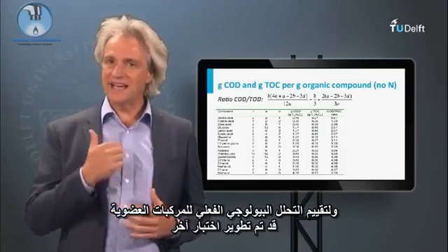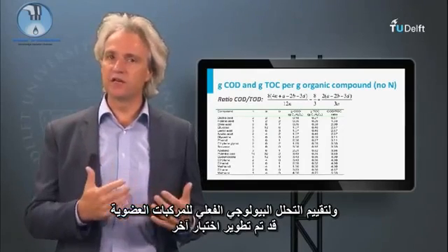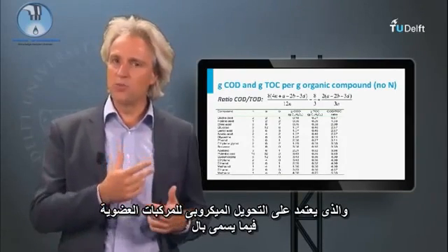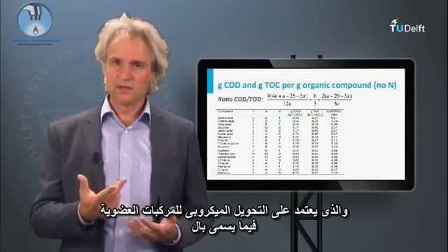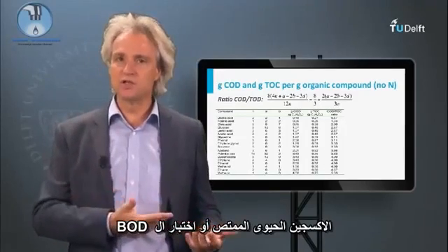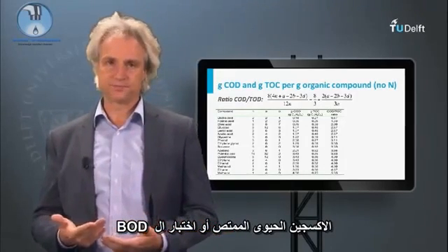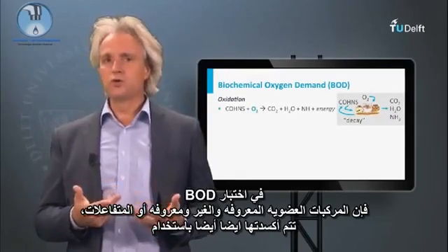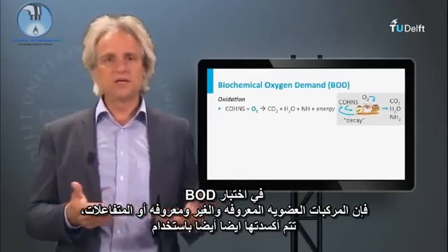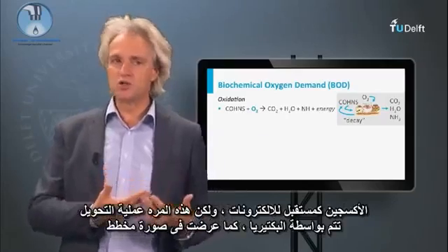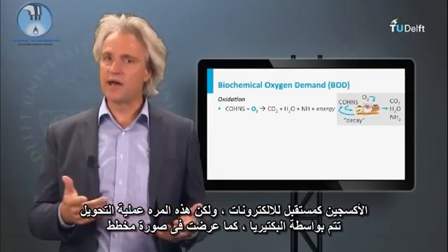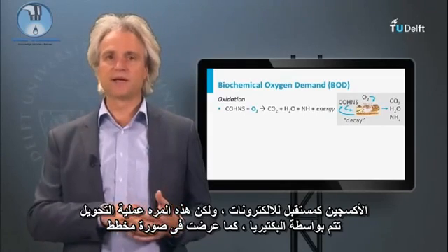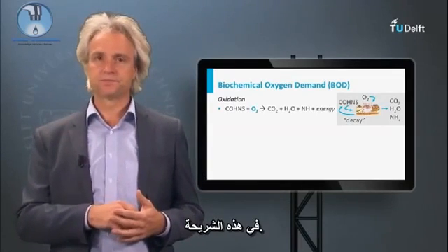To assess the actual biodegradability of organic compounds, another test has been developed, which is based on the microbial conversion of the organics, and it's called the biochemical oxygen demand, or BOD test. In the BOD test, the known or unknown organic compound or substrate is also oxidized, using oxygen as electron acceptor, but now the conversion is performed by bacteria, as schematically presented in this slide.